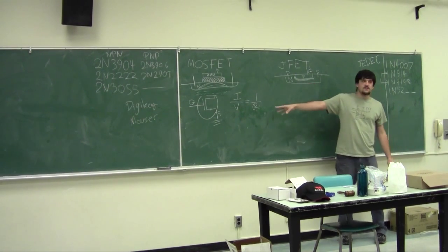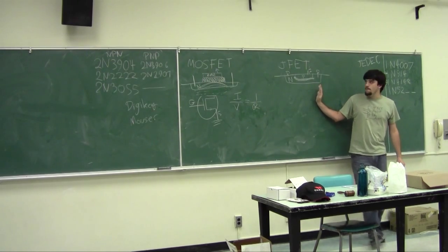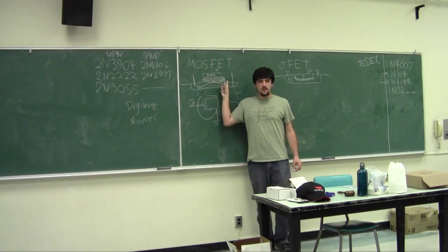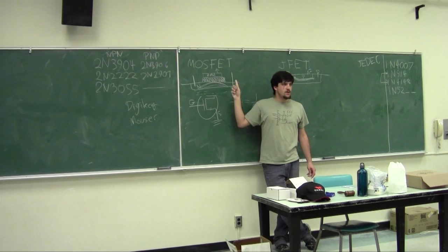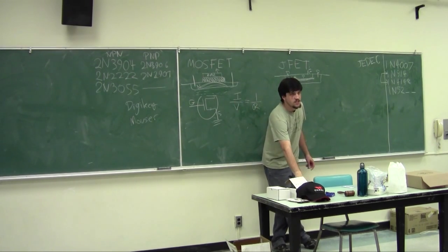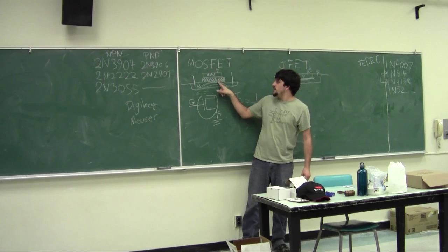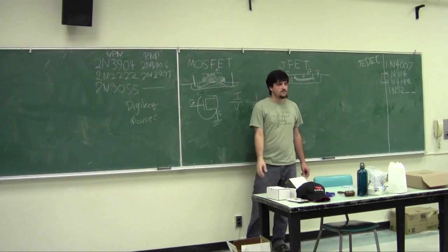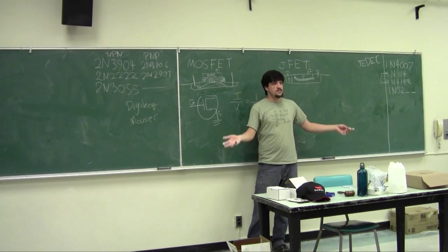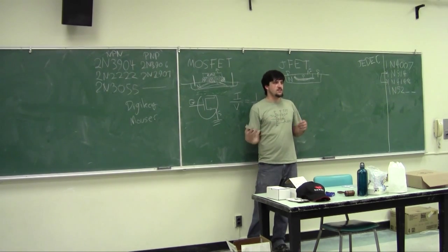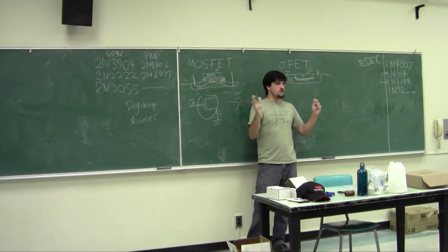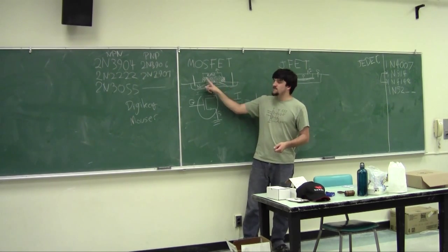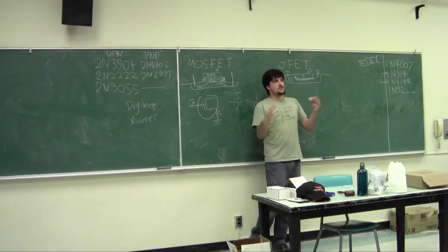Advantages of the JFET over the MOSFET is that it's much, much more robust, right? When we're talking about a microscopically thin layer of insulator here, the static voltage of your hand touching the table is enough to break down this insulator, right? Which then ruins the MOSFET. That's why every single piece of electronics you've ever bought, like a hard drive or a graphics card, always comes in those light gray bags that have all the warning stickers on them, ESD, sensitive material, blah, blah, blah. It's because these very, very thin gates are very easily destroyed.